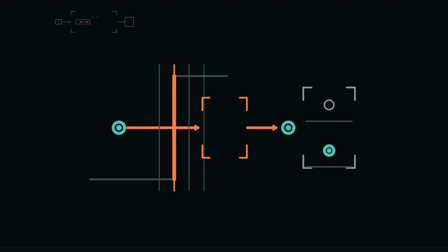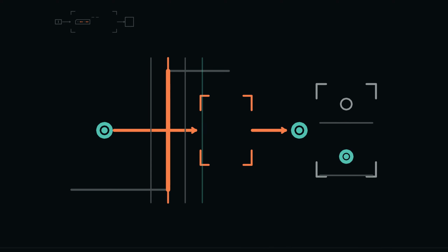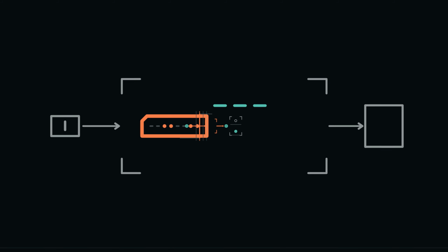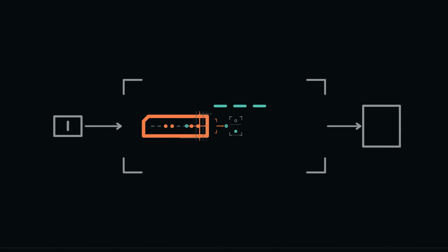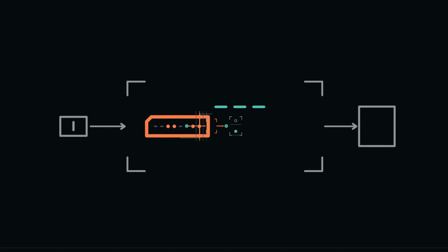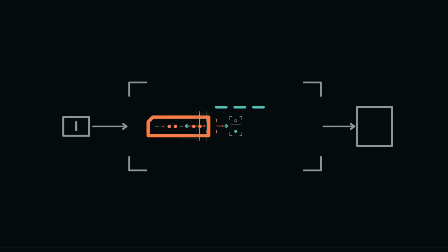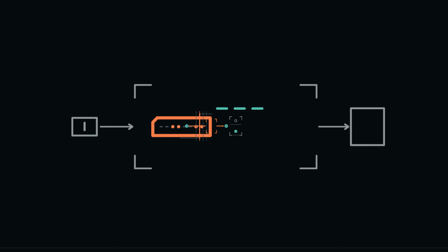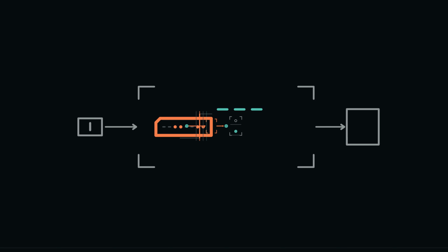The timeline closes around one precise contract. Data may change and settle between active edges. Setup and hold intervals protect the capture boundary. At the edge, accepted D becomes the next stored value. After propagation delay, Q presents it. The before and after ledger prevents old and new state from being blended into one vague motion. We now have disciplined 1-bit storage. The next step is to repeat it across 8 ordered positions and then feed stored state back through a next state rule.